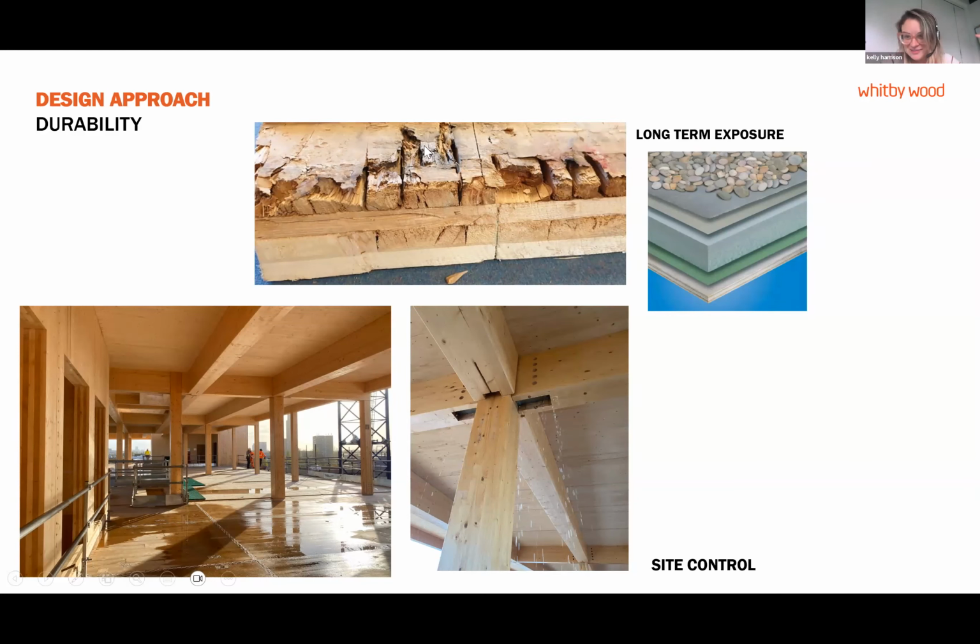Let's also say, if this was a concrete slab, the cover would have gone on, the rebar would have blown as well. It's not just a timber issue. This is the workmanship of the waterproofing issue. But the thing is, we can't see it, and we need to make sure that we're not losing our structural strength if something happens. And so we need to think about how we detail this. We need to have falls on a roof, really. No other way around it.